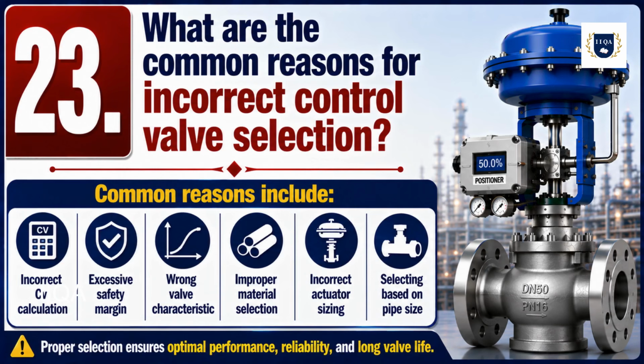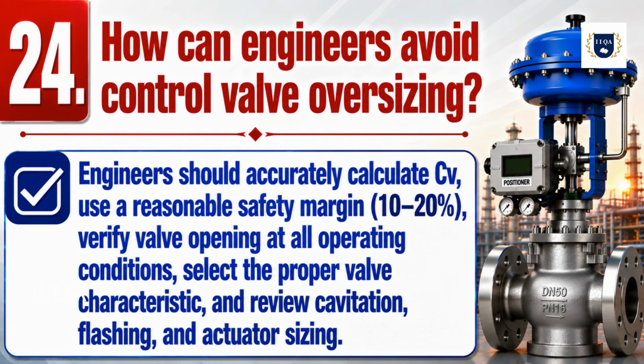23. What are the common reasons for incorrect control valve selection? Common reasons include incorrect CV calculation, excessive safety margin, wrong valve characteristic, improper material selection, incorrect actuator sizing, and selecting based on pipe size. 24. How can engineers avoid control valve oversizing? Engineers should accurately calculate CV, use a reasonable safety margin, 10 to 20%, verify valve opening at all operating conditions, select the proper valve characteristic, and review cavitation, flashing, and actuator sizing.